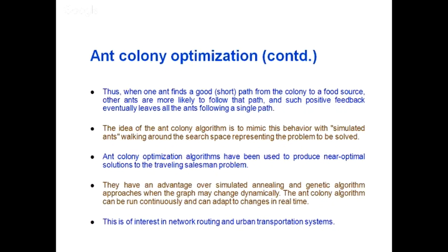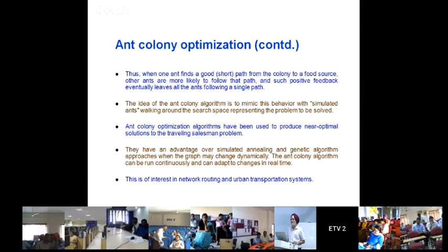Now what are the constraints? What can be the constraints? Constraints are that I have a limit on the V, or V I can convert in terms of pi d n. D is fixed, so I can convert V in terms of n RPM, which is directly controllable. So I have a limit on the RPM. One of the constraints is that I can have a minimum RPM of, let's say, 40 RPM and a maximum of 4000 RPM. So I say n is more than 10 and n is less than 4000. Two constraints I have put on n.